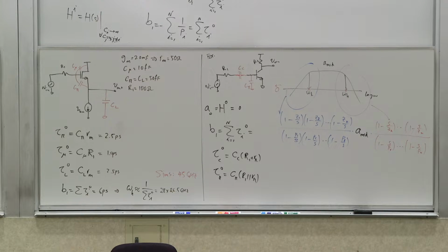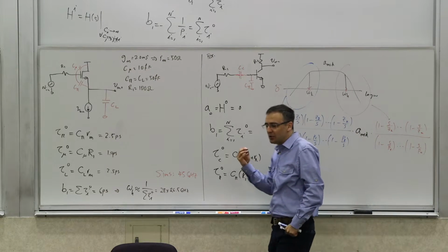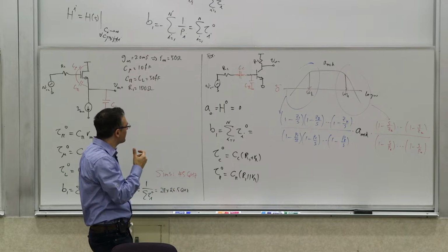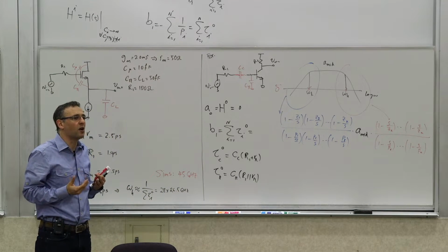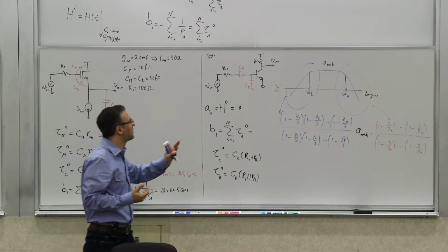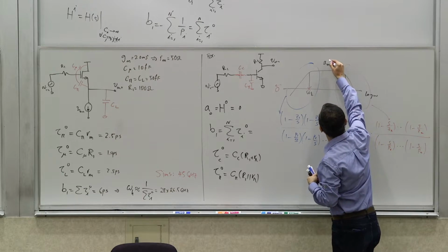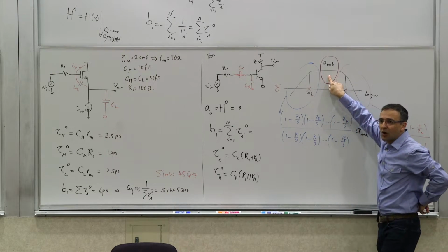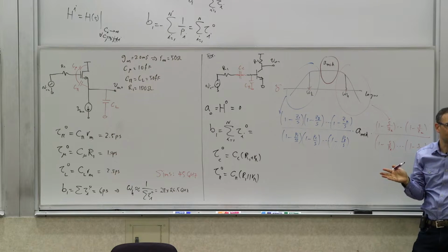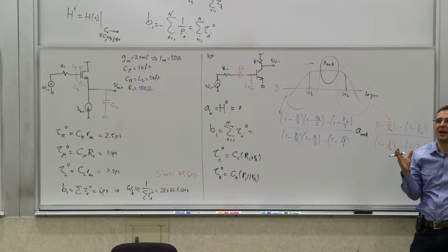Okay, so you can see that, right? There are two parts. There was this kind of factorization that we formed. But now you can also do it in circuits itself. You can be judicious. You can say, okay, which of these capacitors, when I am in mid-range, so when I'm here, if I've properly designed this, some of them can be viewed as short-circuited for the most part, and some of them can be viewed as, up until that point, pretty much open circuit, right? Because you're getting flat response there.